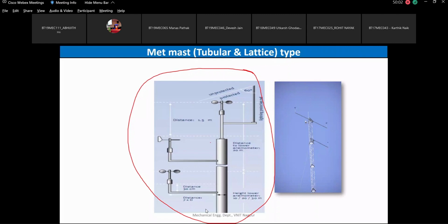And the lightning protection rod you are using over here, obviously you have to use it. Then a 60-degree inclination angle we have to maintain. From here you measure 60 degree, and the height you have to maintain is 7 times the diameter.